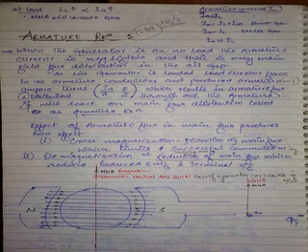So, can you neglect it for analysis? Finally, the load current is nothing but the armature current, right? When you load the machine, whether it is a generator or a motor, the load current is nothing but the armature current. Whenever you say armature current, it is due to load. Whenever you connect some load, the load current flows from the armature. Both of them. Now, what is armature reaction?